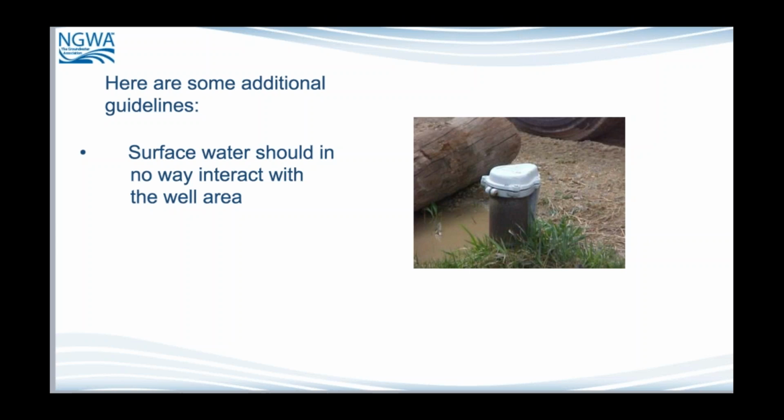The newer wells have all been what they call pressure grouted, pressure sealed for the most part. That's been the required practice for, I would say, more than 20 years. What that means is that they run bentonite, which is a Wyoming clay that swells up all the way around that casing, basically down to close to where the aquifer is, and seal that up. As any groundwater or moisture interacts with that bentonite, it swells up to about 12 times its original size, seals any cracks and voids, and doesn't allow moisture and water to go down along the outside of that well. In the old days, all they ever did was shovel what they called cuttings, which are the actual excavated materials, back in there, and those sometimes can be quite porous.